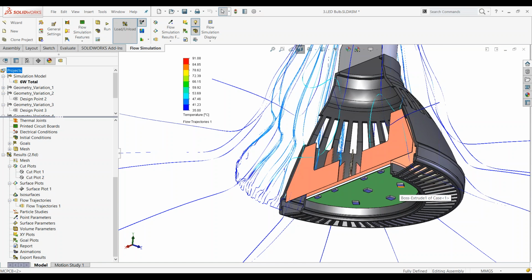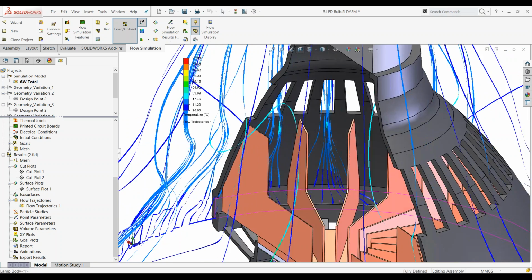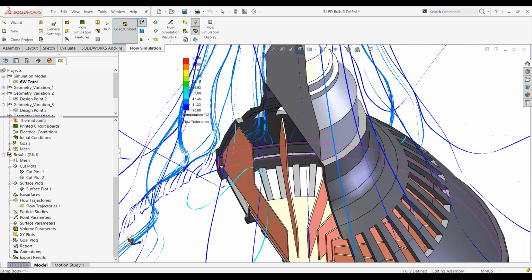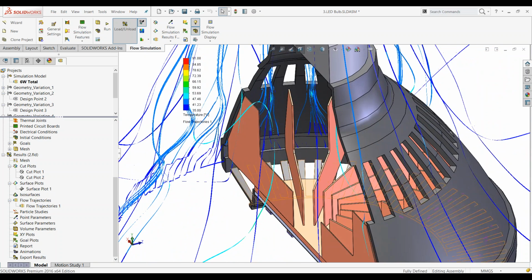In this case, geometrical iterations for different sizes and different numbers of fins, to understand the effectiveness of the cooling. You're also understanding the ventilation in the system, to see whether there are any recirculations or whether all the flows are flowing out. We are able to release the flow away through these particular openings and out of this exit in the models.